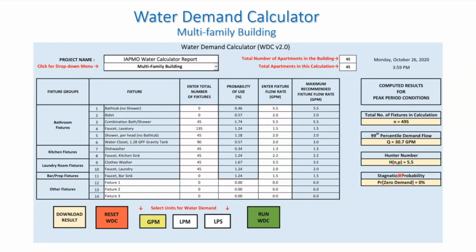So this is the first time since the 1940s that a plumbing code has ever put something forward to revise that design curve. This brings the design curve into the current century. You see these flow rates are very conservative. These are water conserving flow rates for water conserving plumbing fixtures. That was intentional in this design.